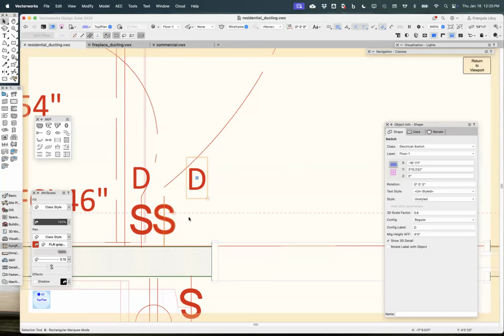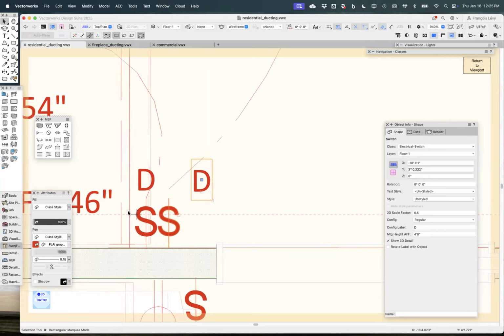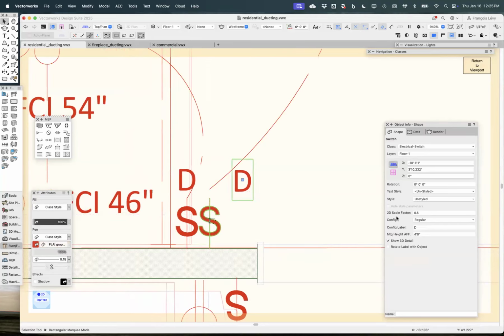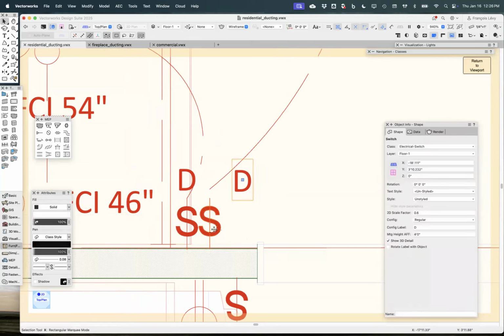And so I make it 6 point text, and that covers the size of this note, or that note. And then I make it 0.6, and that covers the size of the graphic. That S is not actually a piece of text, it's just a polyline. And then what I find is if I space these 2.5 inches apart, or I guess these are 2 3/4 apart, then the 2 plates will be touching in 3D.